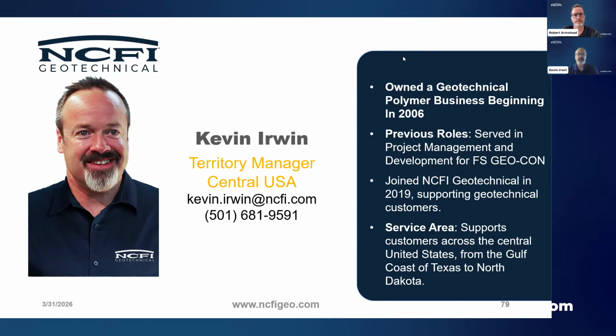We started looking at causation for that, and what we determined, and proved out to be the case, is that we had gotten a hydrostatic lift through our deep injection process. There was enough water under the slab that we actually lifted the slab by pressurizing the water, and then over the week that we were gone, that pressure dissipated into the surrounding soils. So, yeah, it can create a lot of pressure and enough pressure to lift.